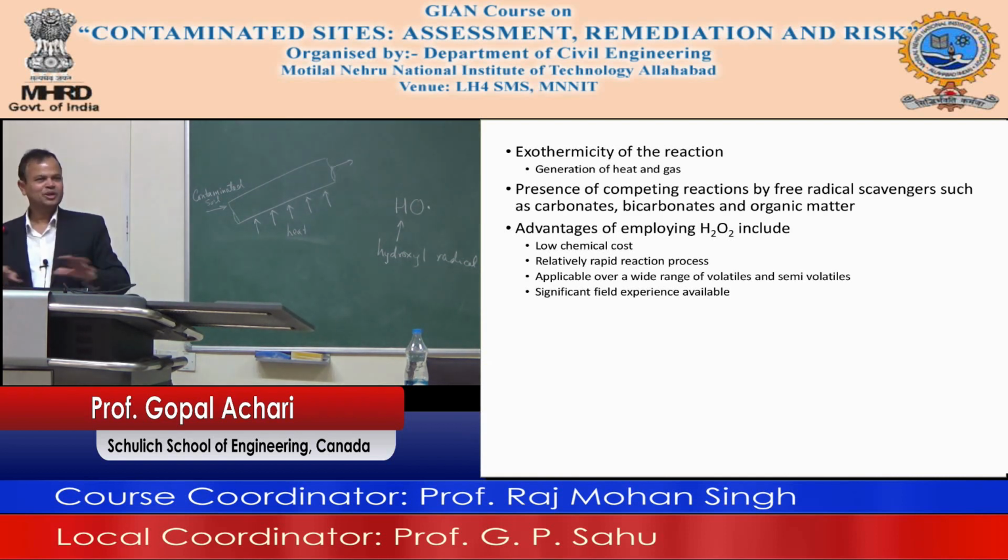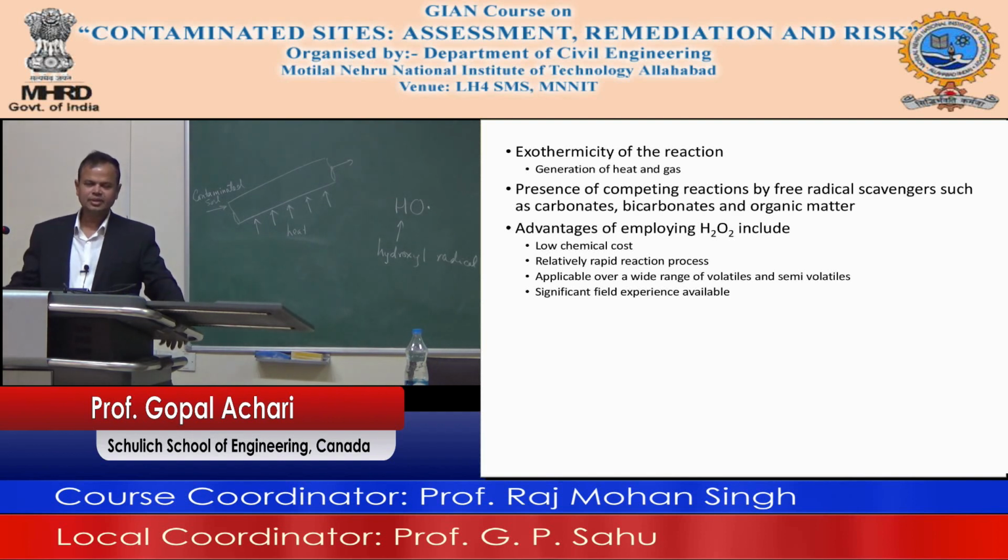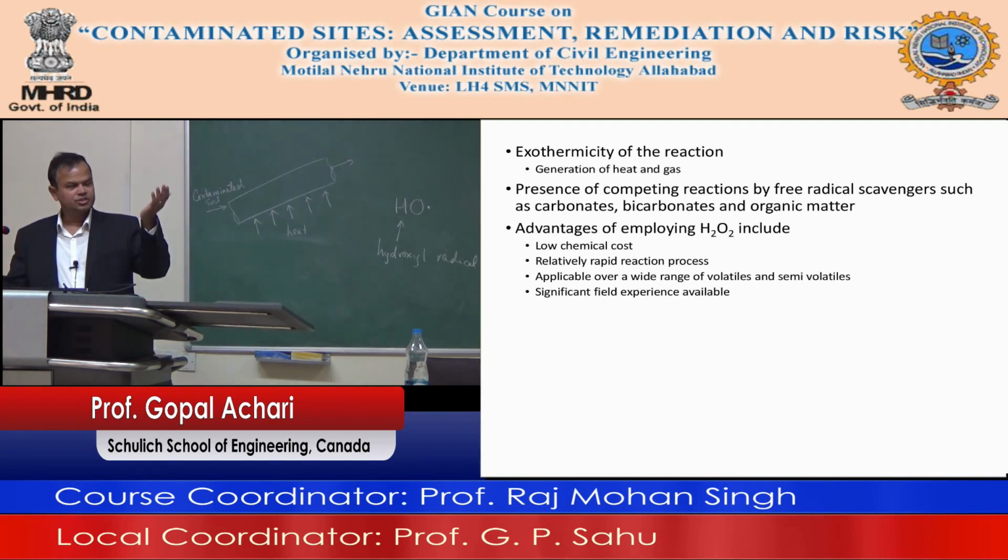If you apply enough pressure, you may even be able to fracture it, which, if the soil condition needs some fracturing, you can fracture the formation, break it out, and apply the hydrogen peroxide and force it into the pore spaces. Hydrogen peroxide will eventually break down to H2O and O2, and the O2 is beneficial in getting the dissolved oxygen concentration up and getting some biological activity going longer term, and whatever it can oxidize, it oxidizes. Got it? Any question on that?